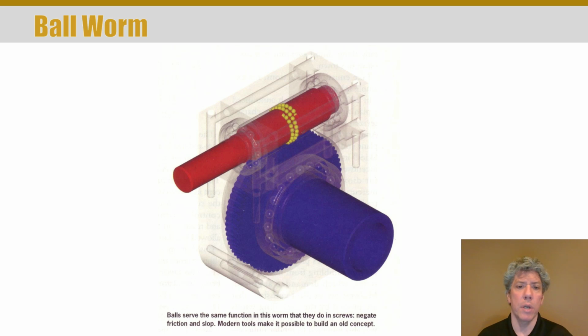And so as you turn the upper shaft, the red shaft, the blue shaft rotates, and this acts just like a worm gear set, except that it has the improved efficiency of a ball screw, and you can typically back drive these, which is pretty interesting, pretty neat. And of course the reason for this is because the ball bearings reduce the bulk of the friction down to nothing, or close enough to it.